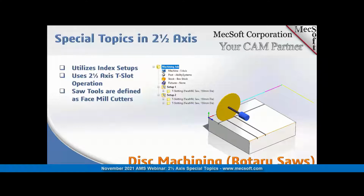Specifically, you can use 2.5 axis slot operations or 2.5 axis profiling operations to cut these using the saw blade. As I mentioned, the saw blade is defined as a face mill cutter with just the large diameter, and the width of the cutter is the flute length of the face mill.